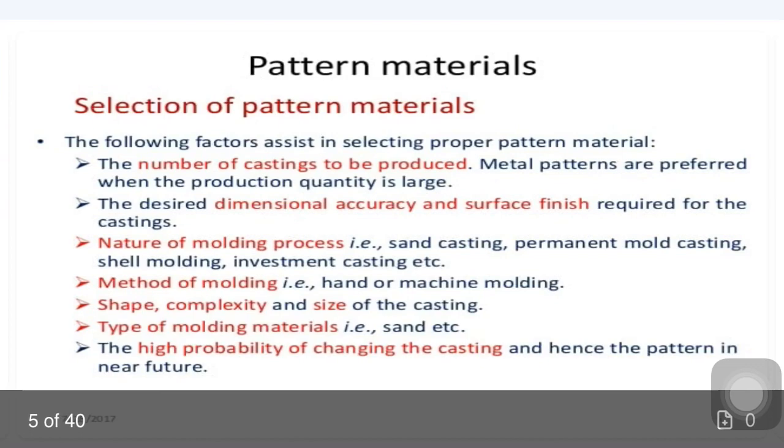After we break the mold and get the cast object, as we go to machining, if we do not provide allowances and we remove the unwanted top surfaces including the sand, the actual dimensions will vary. To overcome these issues, we allow certain kinds of allowances on the pattern material, which will be discussed in the next series of lectures.